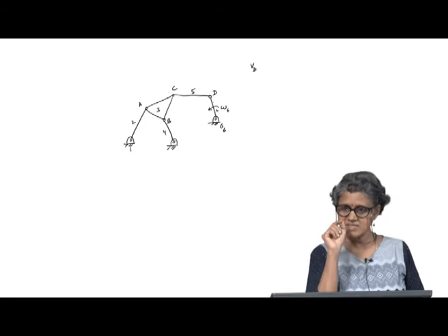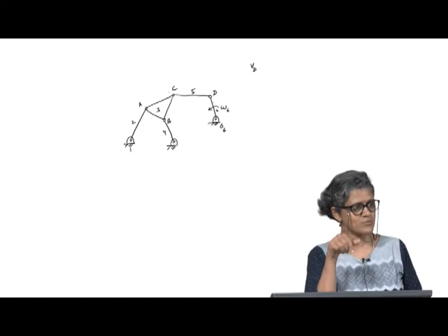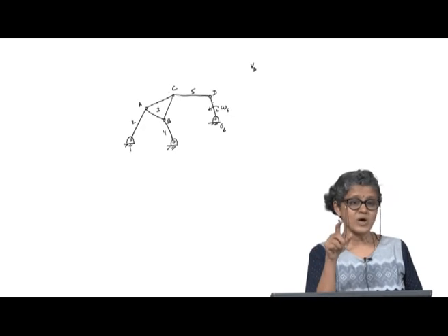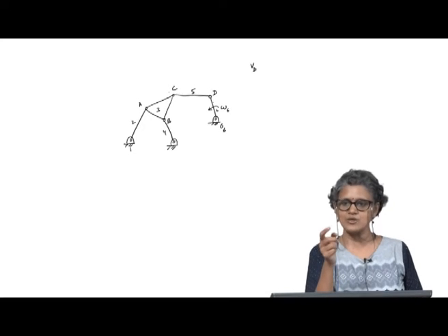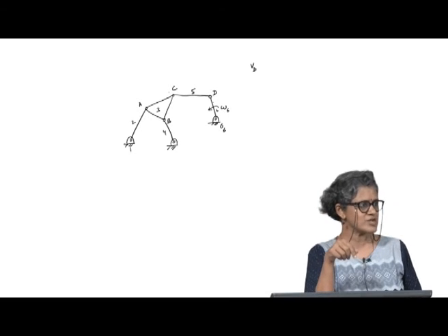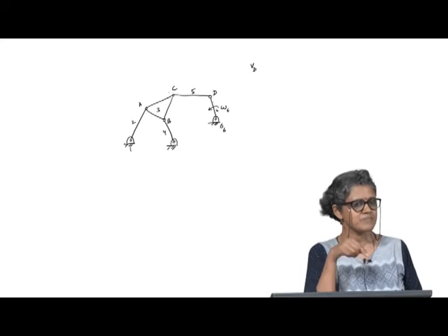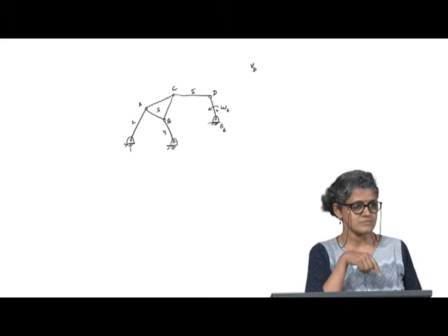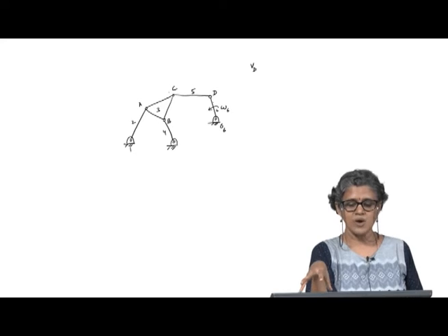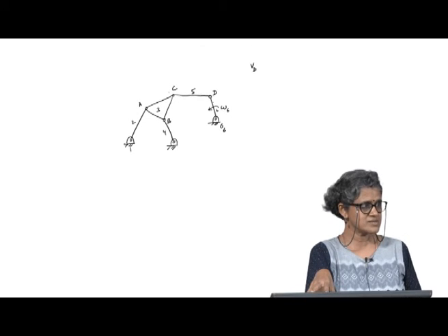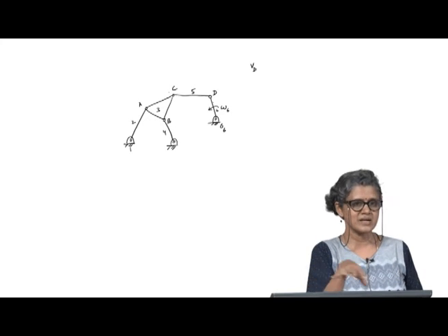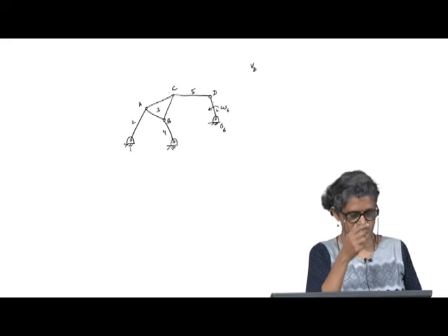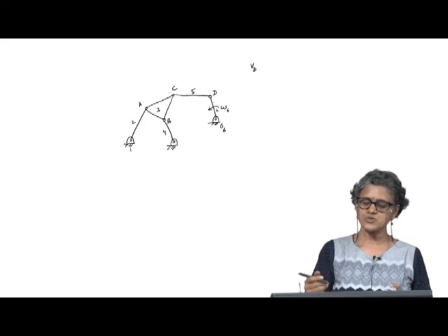In the previous case, C was part of a link which was pivoted to the ground. So, I knew the curvature of its path, and hence I knew the direction of its velocity vector. In this case I do not know that. Okay. So, I cannot even solve this by the velocity difference method, by the relative velocity method. Okay. We will talk about another technique to solve this tomorrow, but now let us see if we can do